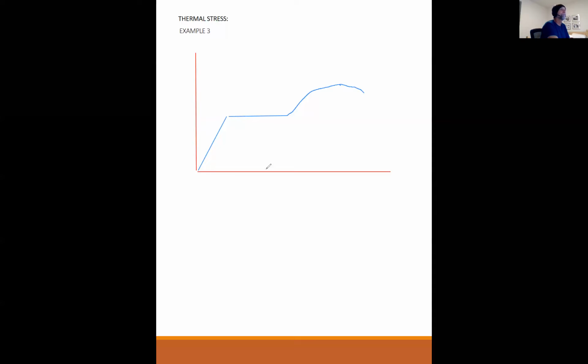So if I go from a very squat and robust section that won't buckle to something that might have a tendency for buckling, then what you might see is at the strain hardening region, it might start failing sooner than if it was not able to buckle like this. But if it gets to be more slender, you may have a sample that barely makes it to yield and then starts failing like so.